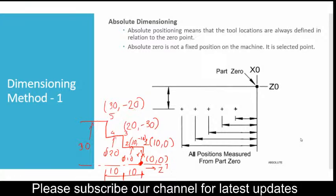We are considering the dimension of point number 5 with respect to this origin point. Point number 4, 3, 2, and 1, all the points we are measuring with respect to the 0, 0 point. So that is nothing but absolute dimensioning. And here, if you read, all positions are measured from a single 0. That is the process here. Okay, so it is basic and simple, I think.